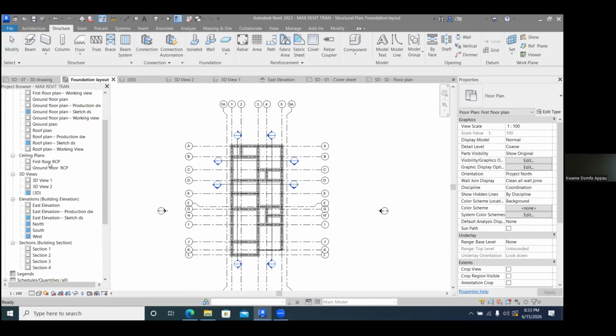I'm asking about the ceiling one, that we need not do that one. You do that one too, because when you do a building, it's not only the floor plan. The floor plan will show you the things that are on plan, like furniture, equipment, doors, and stuff. But the things on the ceiling, like your lighting fittings, your ceiling fans, if you don't do the ceiling plan, how are you going to show them? So that's why it's necessary for you to show the ceiling plan. And of late, people are more concerned about their ceiling with plasterboard ceilings and LED lighting. So you cannot do a design and then leave the ceiling plan out. You have to do them.